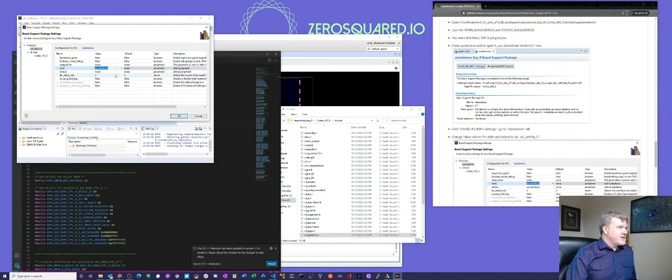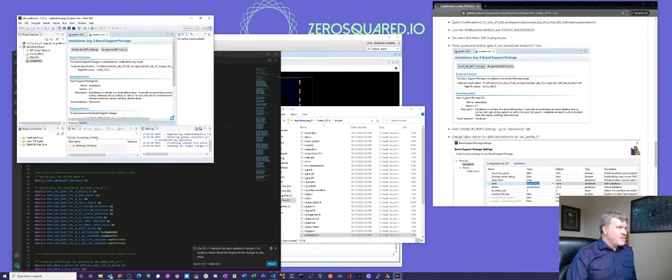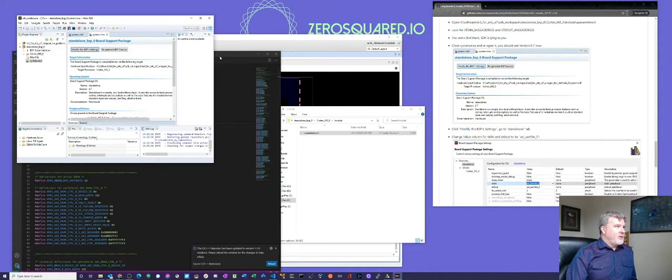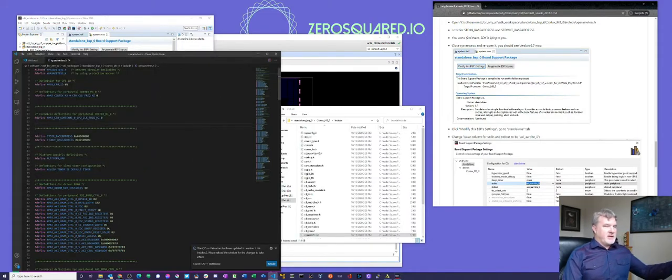So you'll need to change these to AXI UART Lite 0 and hit OK. Now when you go back to the code, you should see your standard in base address and standard out base address populated. If you don't have those, then once you get through the entire flow, the Arty board will be unresponsive.